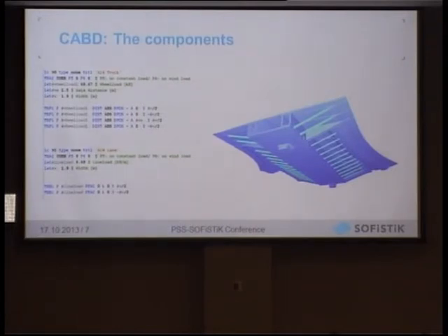I picked two examples. One, of course, because here in Russia I get often asked how about the Russian load trains and Russian specific applications of SOFiSTiK software. As you know that SOFiSTiK has this text input facility for all features, we might simply take one of these input examples and input one of those special trucks which you require, and those load conditions can be used for load stepping, so simple evaluation, and also for influence line evaluation.